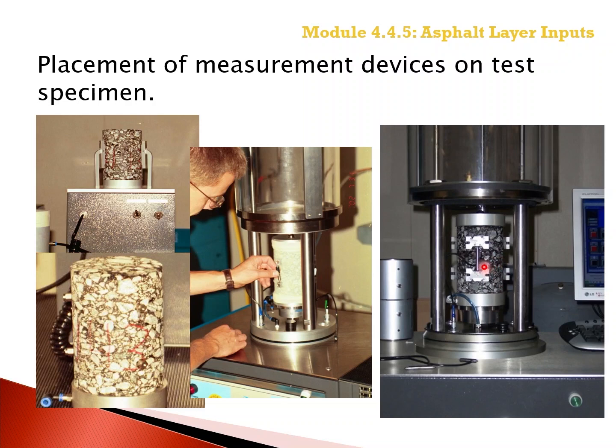There are devices available to assist in attaching the LVDTs to the specimen to ensure the uniaxial deformation devices are attached at the correct location and properly aligned on the specimen to reduce variability of the measured displacements. Reducing test variability means we can test fewer specimens for the same confidence level.